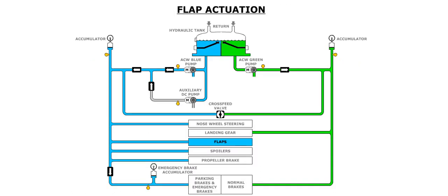The flaps are hydraulically actuated by the blue hydraulic system. It is possible to move the flaps with the green system through the hydraulic crossfeed valve.